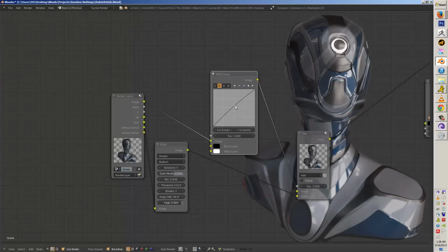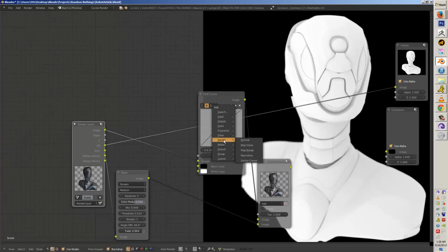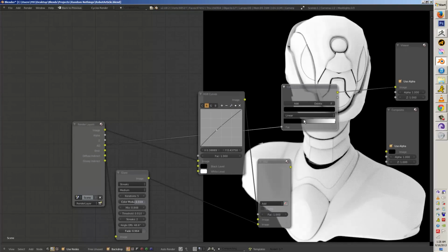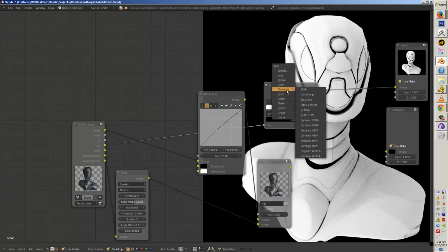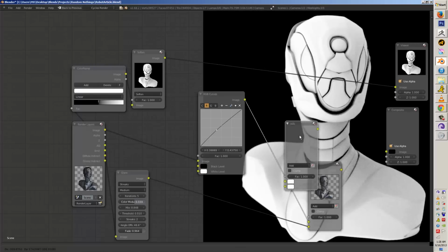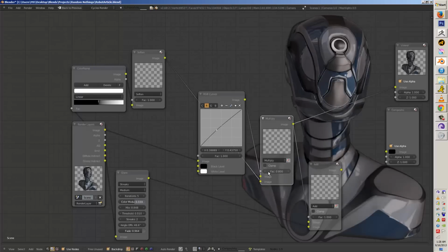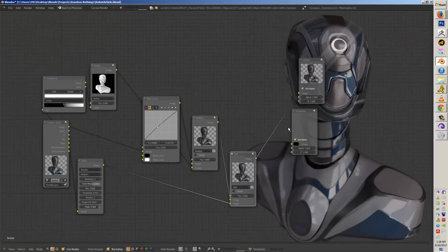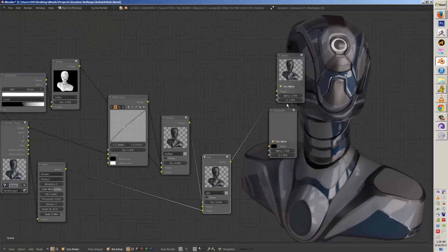So, I always come in, do a little bit of color correction, try to always inject it with red if there's a little too much blue. I always like to take my ambient occlusion pass, clamp it pretty good so the shadows are deep in there. And then I'll soften it, duplicate a node, and before adding the glare, I'll multiply a little bit more AO on it just to really take the image the direction that I'm wanting it to go.